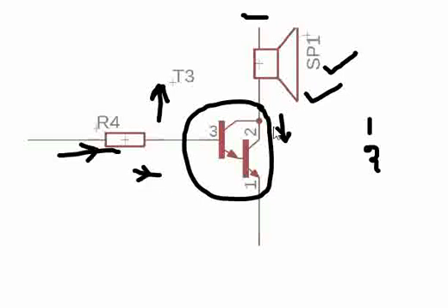The output impedance is low, so it allows more current to flow into the load, which is very important, right? So buffer is another important application of the Darlington pair. This high input impedance and low output impedance is required generally for impedance matching in circuits where you don't want to load your circuit with the output load that is connected, a very important characteristic in circuit design.